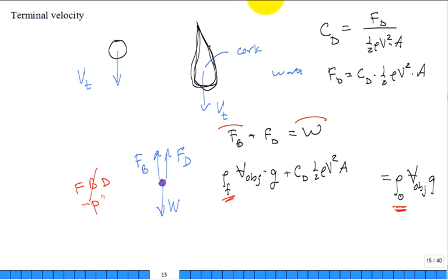A lot of times, we're going to talk about it again because it's so important, we find that this drag coefficient plotted goes C sub d as a function of Reynolds number. It gets down into this region right in here. When it's flat, what does that mean about the drag coefficient in this flat region?